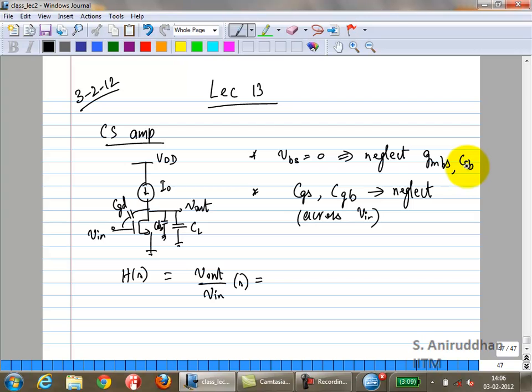So how do you find out the poles and zeros? This is a little bit more complex, right? The total capacitance at this node and the total impedance at this node, right? The conductance. Gi over Ci at any node is going to give you the pole frequency. Okay. What about the zero frequency? How do you find that out?